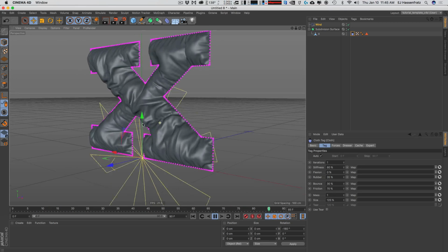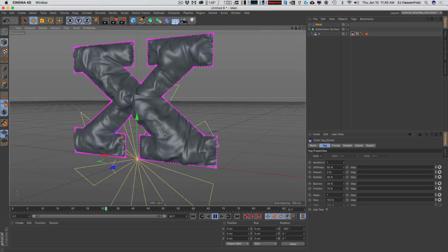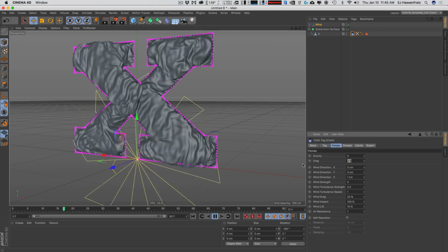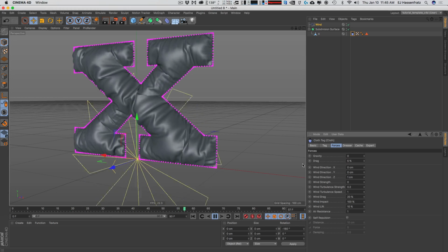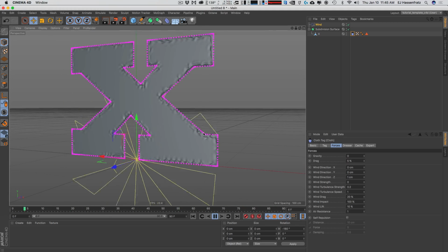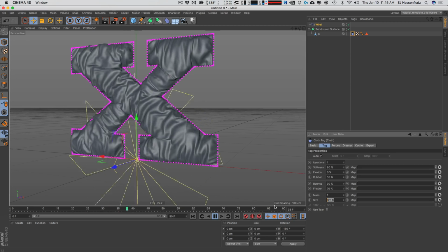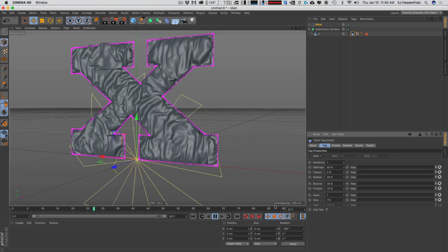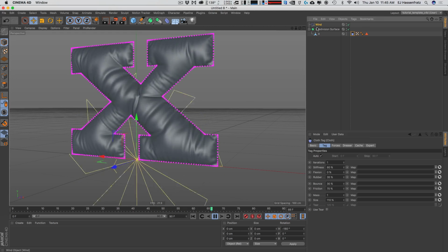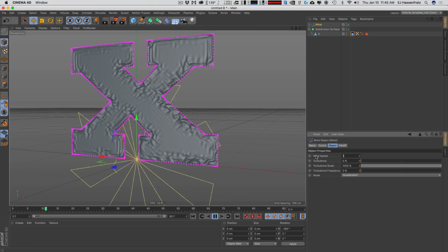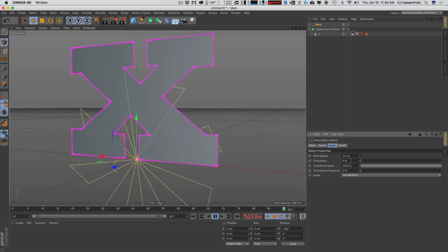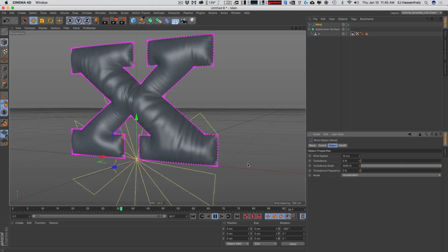And this is looking really nice and ripply and wrinkly. And maybe we go and increase the drag so it slows everything down a little bit. Maybe we bring the size... maybe that's a little bit too much slack. This is a little bit too much wrinkle. Let's bring this down to like 110. And let's bring up this wind strength to maybe 10 to blow that out a little bit more. So now what you're seeing, let's go a little bit higher, maybe 15.